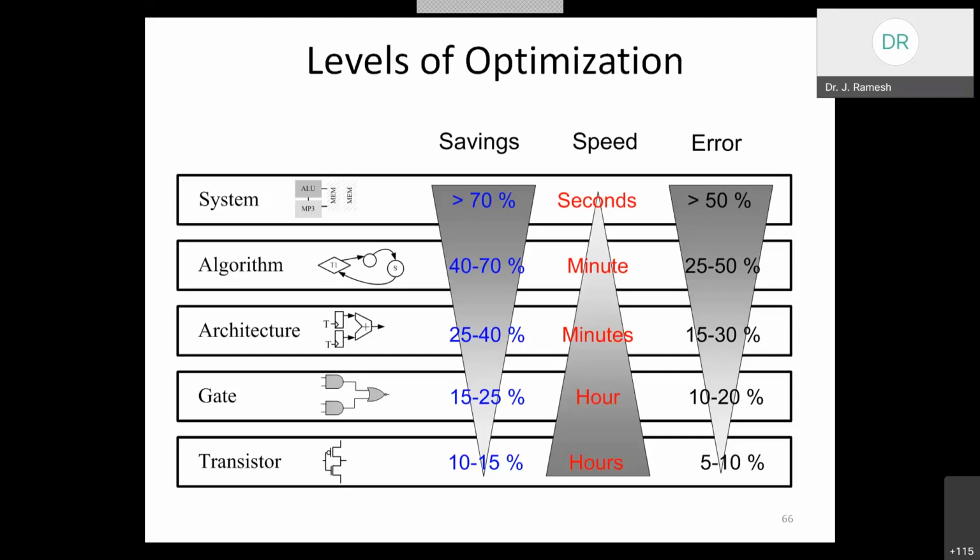For a particular computation, we are applying parallelism. Even though the area is getting increased, the power reduction can be achieved. This loop unrolling technique is an important technique for flow graph transformation.